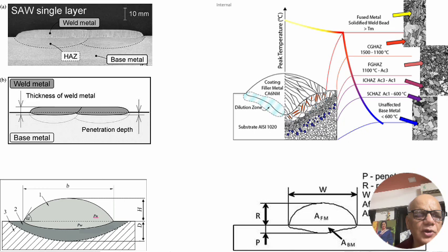So the configuration of this weld profile is very important, and that is where this angle comes into play, because our second run, the second pass, is going to be either on this side or on this side, which we will see in the next slide, and that must get properly fused with this entire line here, as you can see the overlap which has been given here.